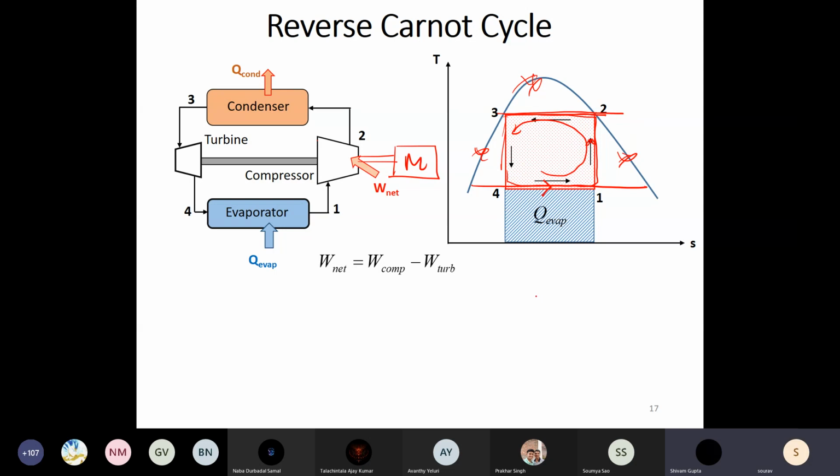Even now we think of the ideal compressor being an isentropic compressor, and the ideal turbine being an isentropic turbine. So for the time being, assume that that is possible with the best efficiency. We can attain an isentropic efficiency close to 0.9 or 0.95. Let's assume that. So what happens is these isothermal processes, this is where the difficulty arises.